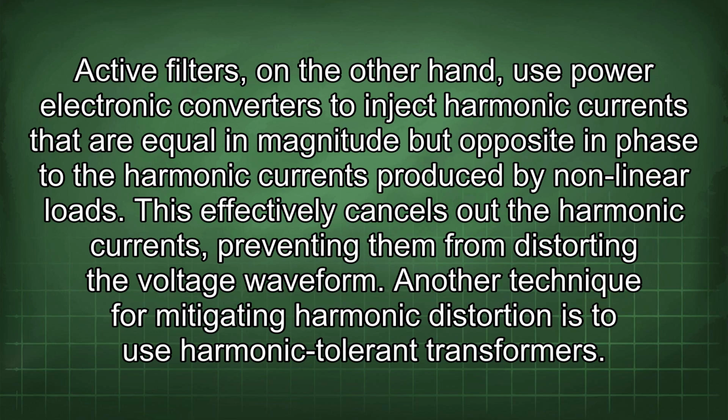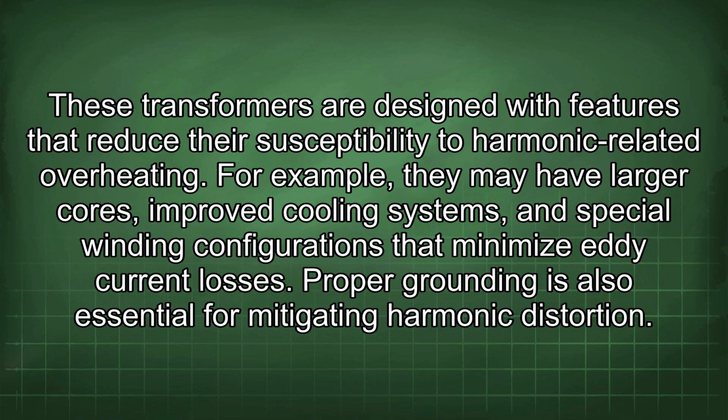Another technique for mitigating harmonic distortion is to use harmonic-tolerant transformers. These transformers are designed with features that reduce their susceptibility to harmonic-related overheating. For example, they may have larger cores, improved cooling systems, and special winding configurations that minimize eddy current losses.